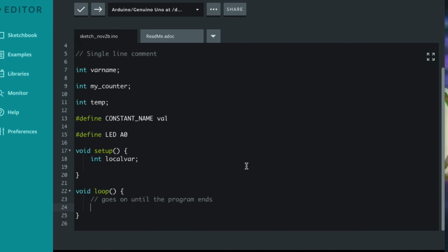And behind the scenes, there is a call to this loop, and it's an infinite loop. But afterwards, it also checks the serial, so it doesn't interrupt checking to see if there's some serial input over the USB or over the pin serial connections, or if you've got any output.